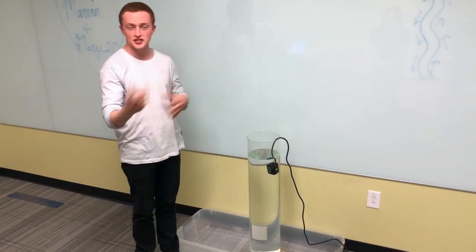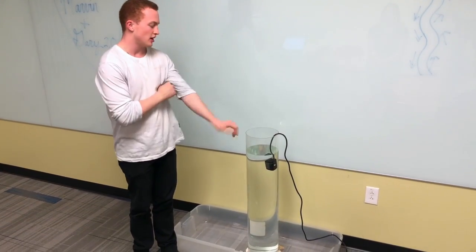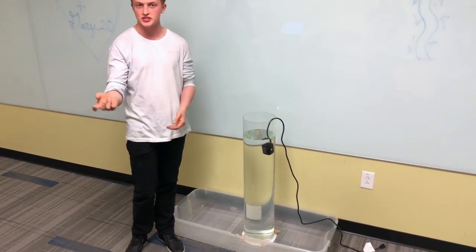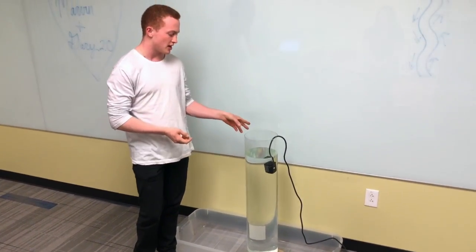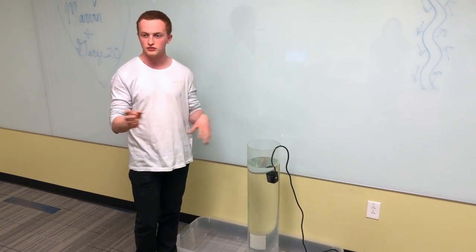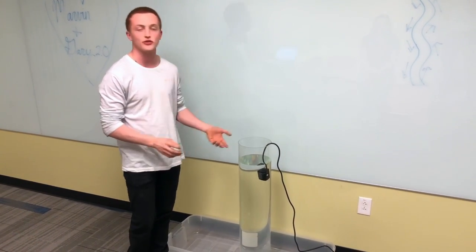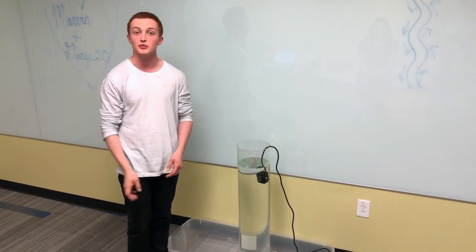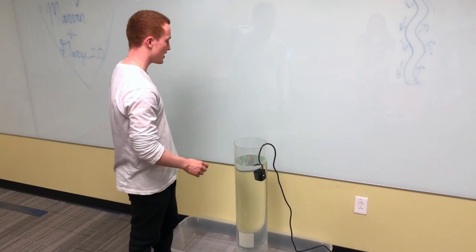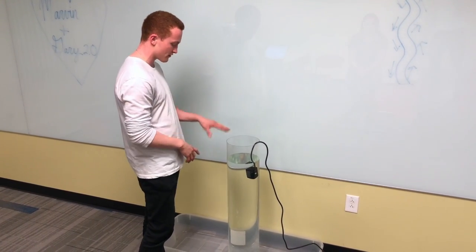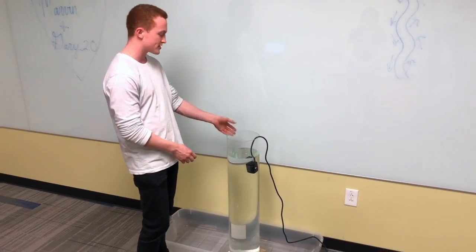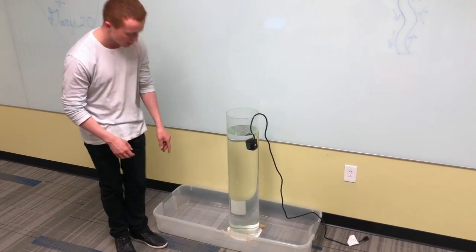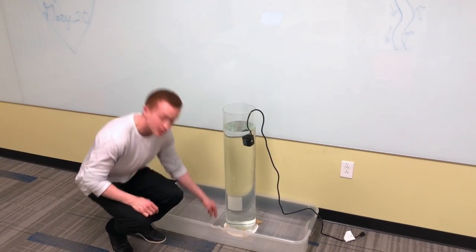All right, so just discussing the environment a little bit more specifically, I'd like to jump into the individual components. The first thing here is the pump, which Laura was discussing a little bit earlier. This pump is typically used in a lot of different home aquatic systems. It's rated for 140 gallons per hour, which is significantly larger than the 18 that we calculated to be necessary. Within the environment itself, there are 2 core pieces of acrylic. One is this 8-inch in diameter acrylic tube. An additional component is a base plate.